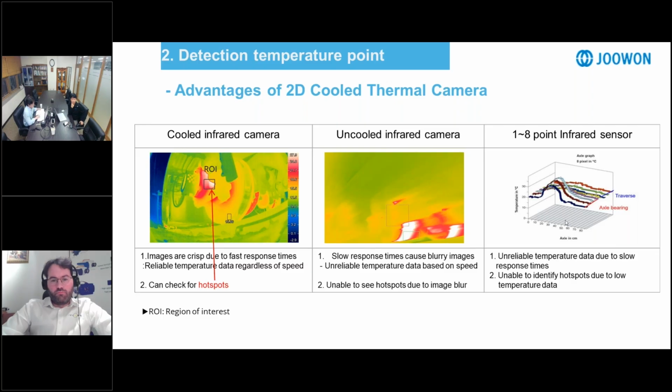And also, this one is the point sensor that I mentioned before, the two pictures, do you remember? By using that kind of point sensors, maybe imagine we are using 8 point sensors, but only 3 point sensors can be used, and the other 5 lines will be dead because of the obstacles. The obstacles could be the bogie structure, train structure, and contamination from dust. So we are focusing on capturing exact and precise temperature measurements. That's why we are choosing the cooled IR camera provided by Telops.